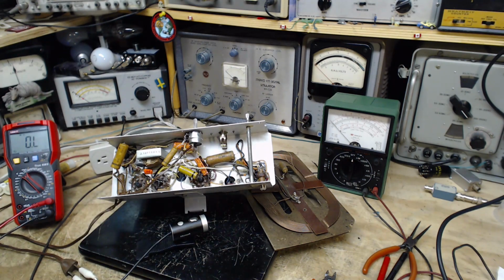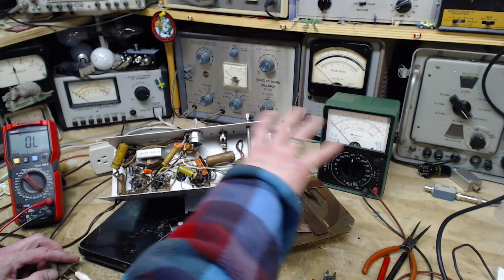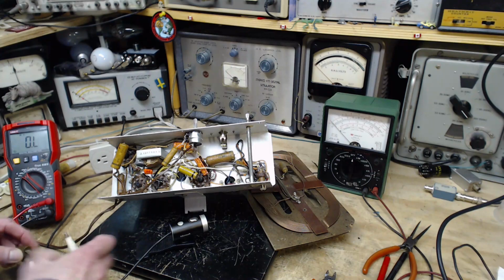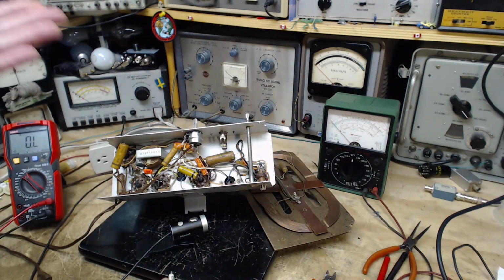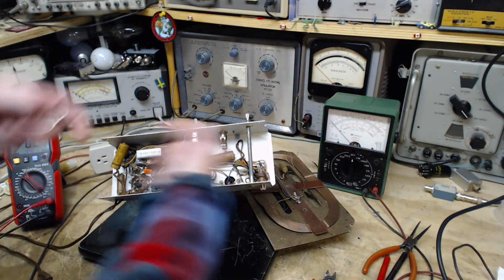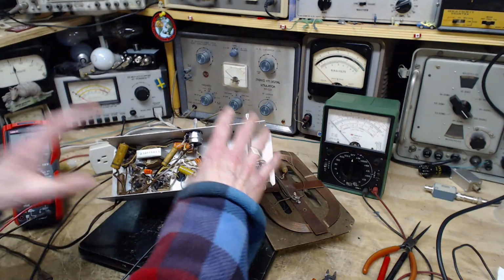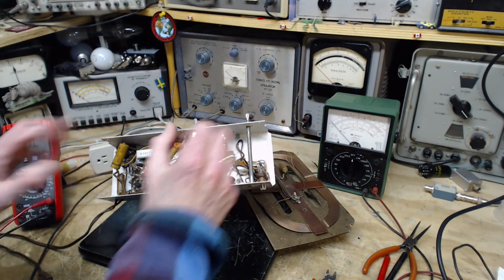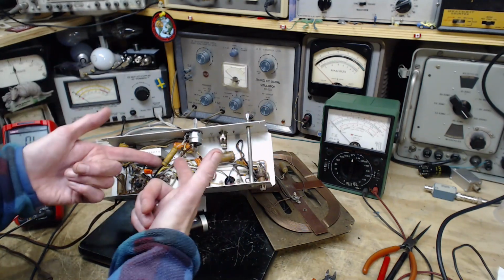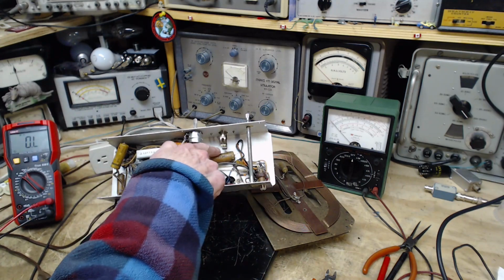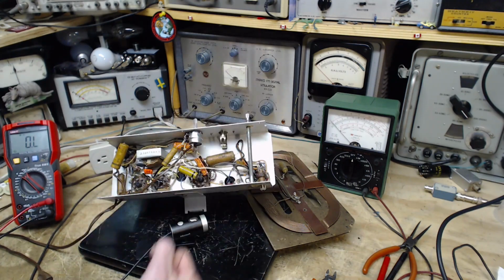The problem with that is if you operate this radio, this chassis is going to be picking up signals, not just from, you know, stuff, but actually from the radio itself, and convey them around, feed them back into other circuits and coils and stuff, along with picking up all kinds of noise. Which, I mean, you don't want some noisy piece of metal laid up against your radio, right? So that's what this capacitor is all about. It's all about grabbing that and nullifying it.